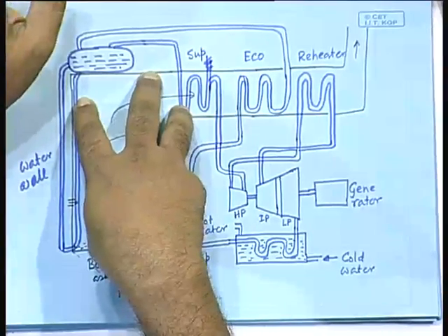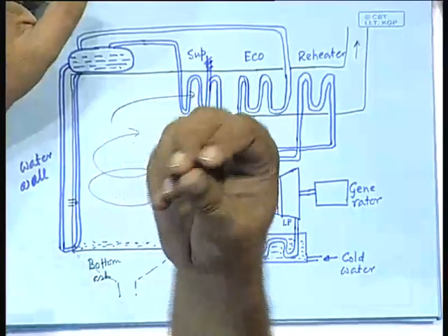Very clean process. If complete burning is ensured, there will be no carbon particles, no suspended particulate matter. Very clean process, and one would really like that. That is why the gas-based power plants in western India are much more environmentally benign. The only problem is the NOx production, because the temperature is high, therefore NOx production is there. But nevertheless, that is much cleaner than a coal-based power plant.